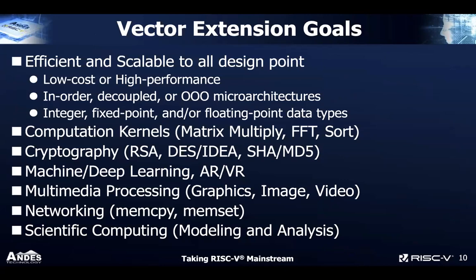Now, let's switch gears a little bit and talk about vector extensions. Vector extensions are designed to be very scalable and efficient at all design points, from very low cost to high performance. They can be in-order, decoupled, or out-of-order microarchitectures, with integer, fixed point, and floating point data types. The nice thing about all this is that no matter how it's implemented in microarchitecture, the same software runs on all the different implementations.